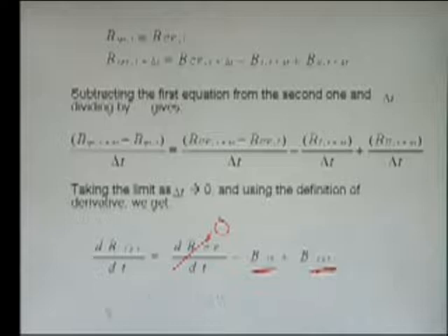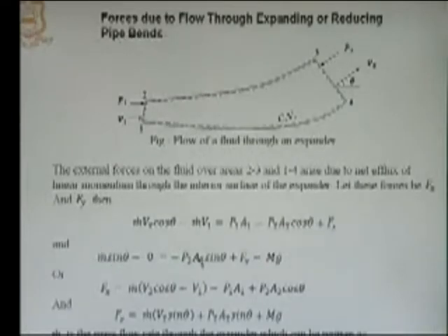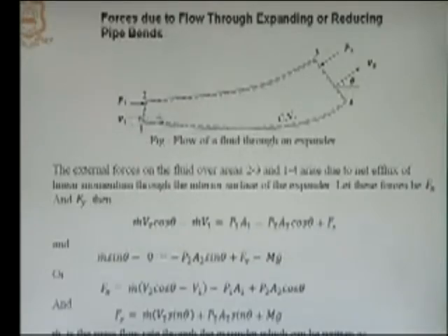right. So, force is equal to this thing, but in this case we have a control volume. So, this is replaced by these 3 terms. In this case the first term will become 0 because flow is steady. Now, we are left with 2 terms, minus B in plus B out. What is B in? Momentum going inside the control volume. So, this is mass multiplied by velocity at which it is going inside the control volume. So, this is minus B in,